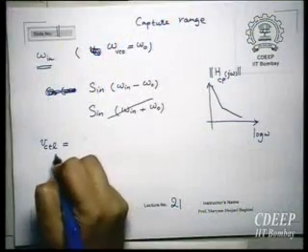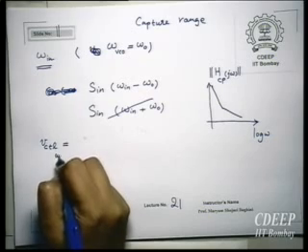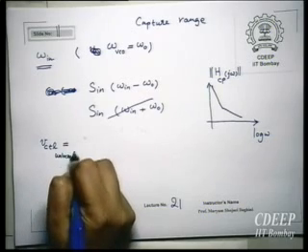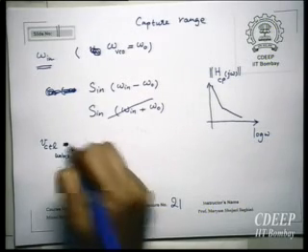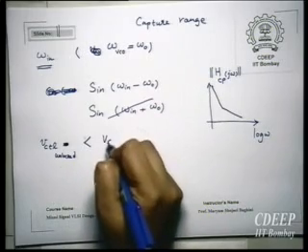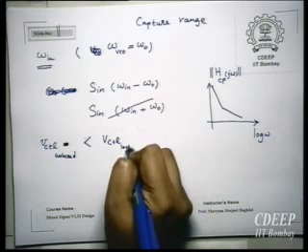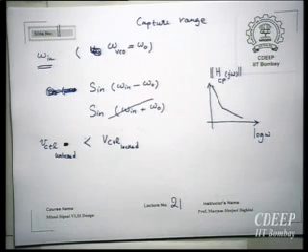That this value, this VCTL for the unlocked condition, will be less than what I get if it is locked. Because in the unlocked condition, even in a steady state, the input will always be a frequency which is above 0.